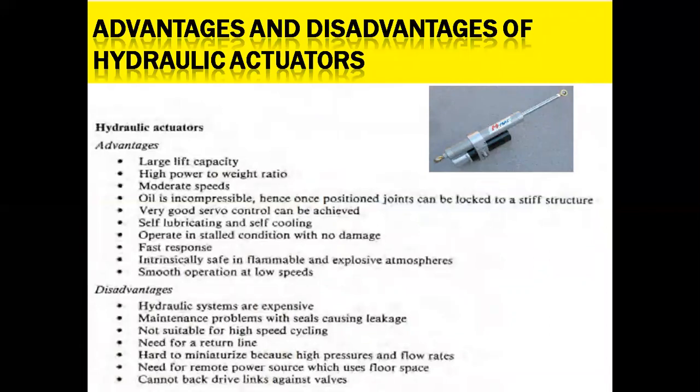Going to the advantages and disadvantages of hydraulic actuators. Among the advantages, it has large weight lifting capacity and a high power to weight ratio, maintained only at moderate speeds because quick actions cannot be performed as in the case of pneumatics.